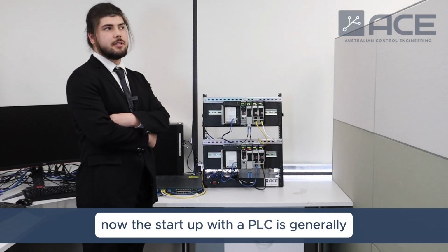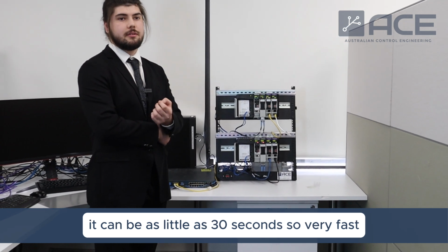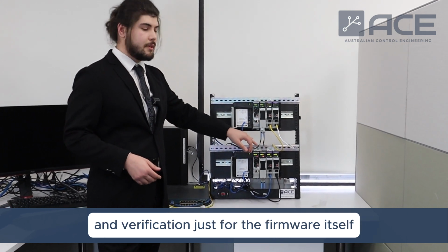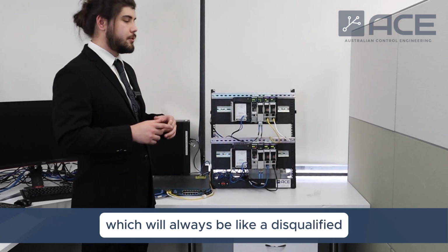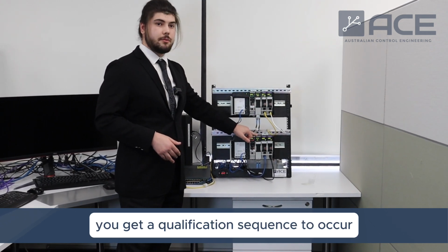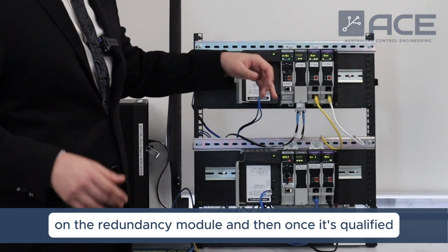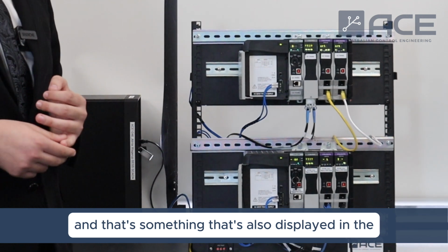well, the startup of the PLC is generally not something that you have, but that would be 3 minutes. To actually qualify, it can be as little as 30 seconds, so very fast. The idea is that it's going through its internal testing and verification just for the firmware itself, and then you'll get a sequence where it tries to identify its initial state, which will always be disqualified, as it is yet to verify that it can retake over control. You'll get a qualification sequence to occur, displayed on the redundancy module, and then once it's qualified, you'll see the sync text appear, and that's when you'll know you're good to go. And that's something that's also displayed in the RMCT as well.